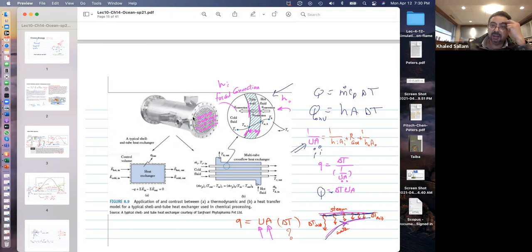All those formulas. And usually the h doesn't come as h alone, it's usually part of a Nusselt number, which is h times a length scale divided by k, some kind of conductivity, right? So anyway, once we get those h's and our conduction for a pipe, you will be able to add these three of them together and say this is 1 over UA. And I'm saying here UA, they are either based on the inlet area or the outlet area.